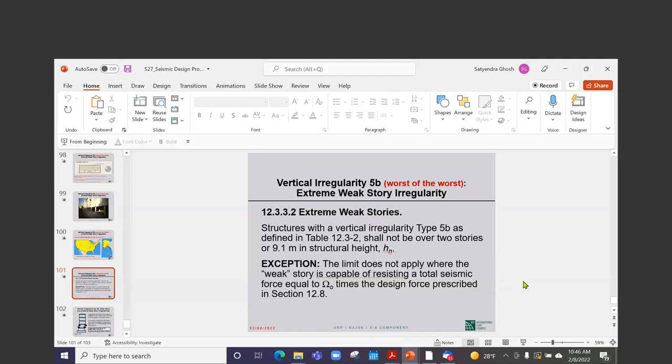But if you want to be code complying, I went over that, I think, on the first day of Seismic. There are serviceability load combinations in BNBC. So look at that. It tells you to keep gravity on the structure. I think it is D plus 0.5 L is what I recall. And that is not a bad idea. That much dead load will be sitting on your structure anyway. It is a question of whether you want to keep the full design live load or some fraction thereof, and 0.5 L is probably as good an idea as any.